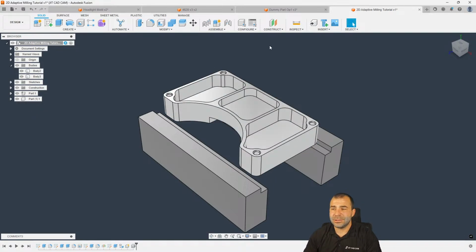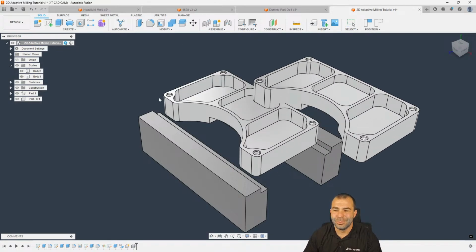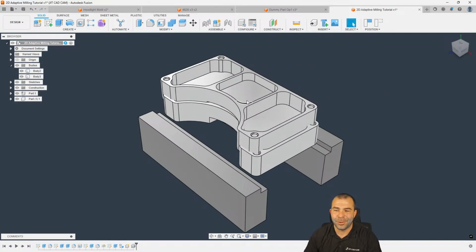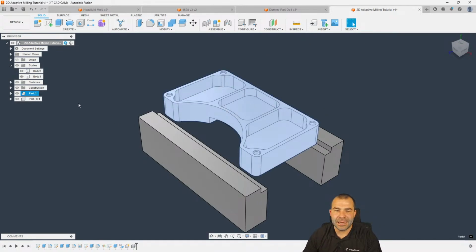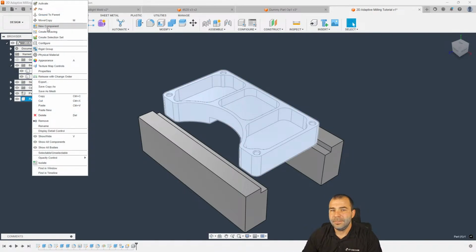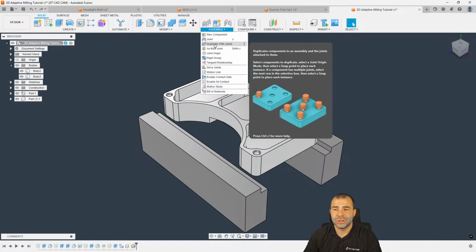So what we're going to do, and somebody pointed this out when I was talking about model on Wednesday, is so that your parts don't get moved around. As you can see, I can click and drag one, but I can't click and drag the other. Well, the original part is anchored. Now, my second part is not anchored. So it's up to you which way you go about this. We made a direct copy. I could actually go in and ground this. So now neither part can be clicked and dragged, right? Another way to go about this is we could actually do a rigid group.